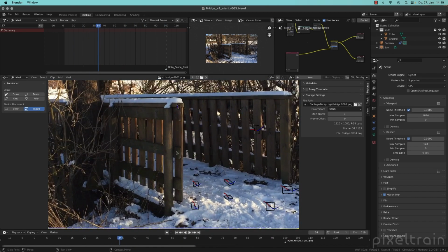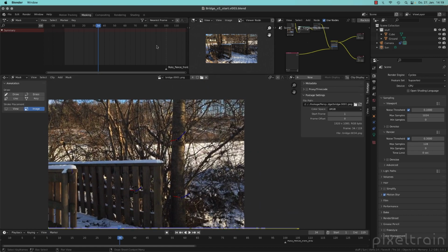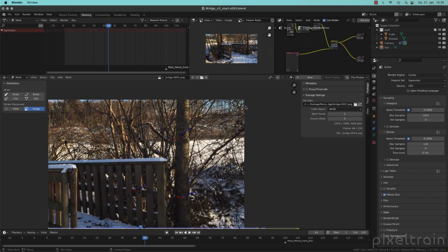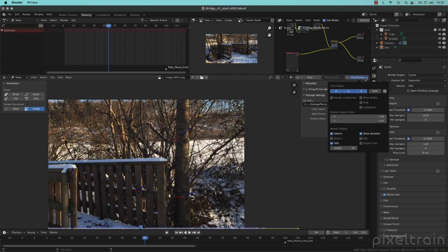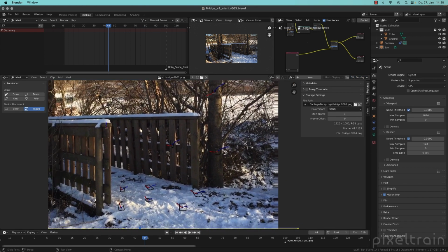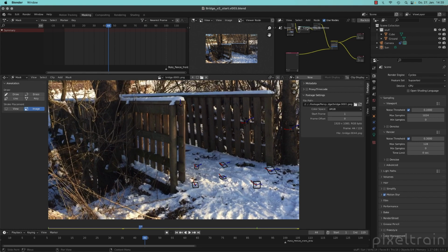But we will see, and this is now a pitfall, you will see that the plate here, look at that, has no artifact. And this should be the alarm clock for you. So what you see here is the original plate. Be aware of that. So go to clip display and say we want to render the undistorted plate. Now you're really seeing what you later get. And this can change a lot, like you see here. So make sure that you see that.